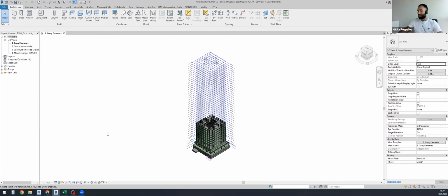So yeah, this is the correct model. Here you can see the construction BIM model example. Our company created predefined templates for Revit, for different versions of Revit. So it's pretty simple to use on the construction side. We have predefined the main 3 steps to create a construction BIM model. You just copy elements, divide them into parts or pours, and then export it to Navisworks and continue developing and adding attributes or additional information that is created on a construction stage.